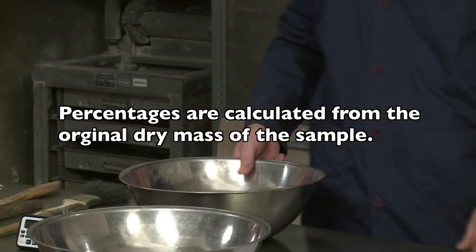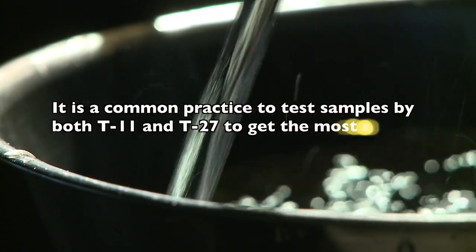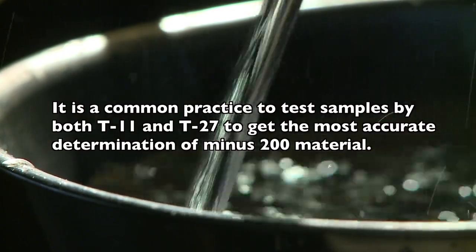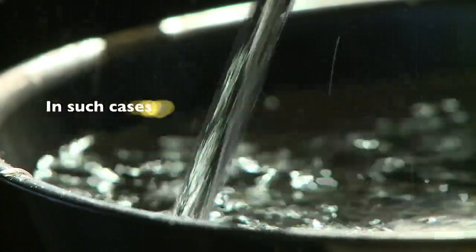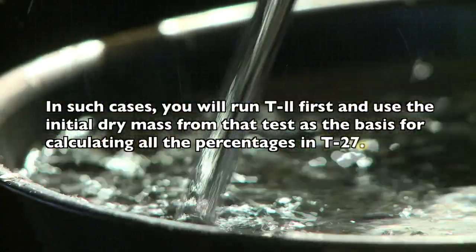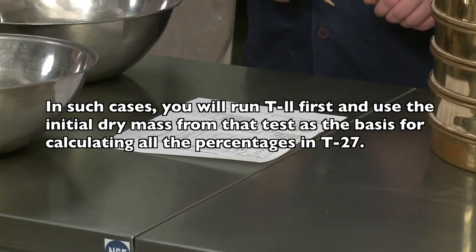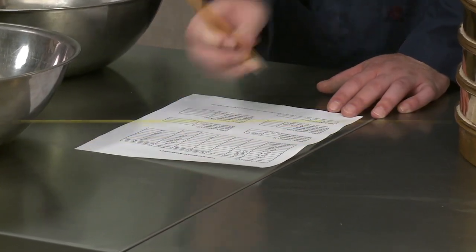Percentages are calculated from the original dry mass of the sample. It is a common practice to test samples by both T11 and T27 to get the most accurate determination of -200 material. In such cases, you will run T11 first and use the initial dry mass from that test as the basis for calculating all the percentages in T27.